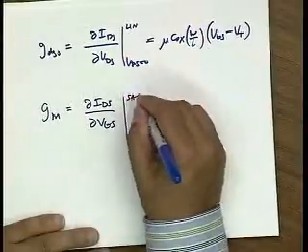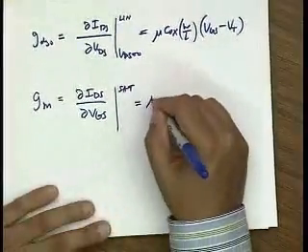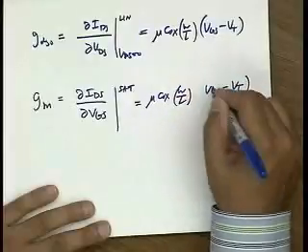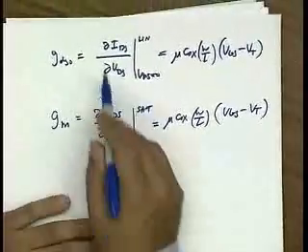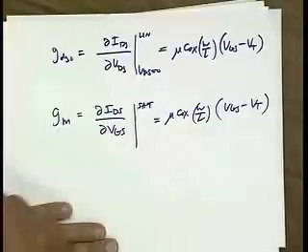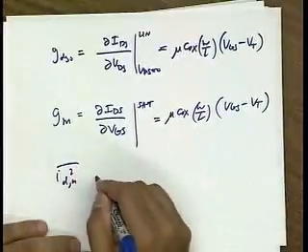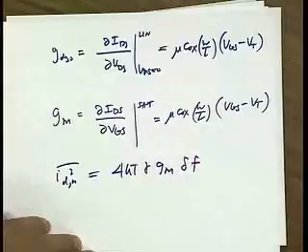This is a saturation region equation to find the GM. That's also given by mu C ox W over L (VGS minus VT). Okay? So when people made this observation, they said, aha, that's nice because who knows what GDS0 is anyway? I know what GM is, so I'm going to use GM. So in this equation, for the drain thermal noise, they said it's 4KT gamma GM delta F.